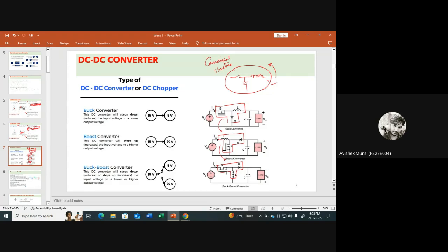So if you go through this canonical structure and move it in an anti-clockwise way, you can see that the buck can be converted into boost, boost to buck boost. Okay, is it clear? Is it clear to everyone that this is a canonical structure? If you consider it and move it anti-clockwise, then we will get every converter over here. So this is just a trick to understand the structure of the converters.